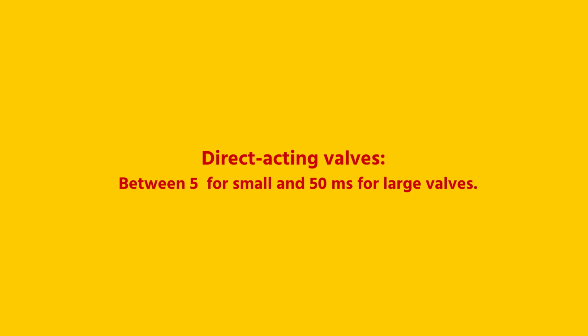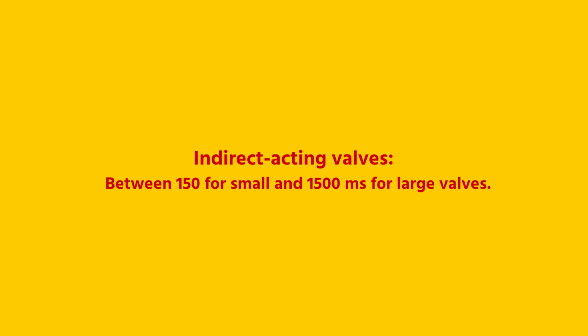Common response times for small direct acting valves is 5 milliseconds, and for larger ones roughly 50 milliseconds. For indirect acting valves, typically 150 milliseconds for smaller valves and 1500 milliseconds for larger ones. Keep in mind that a small response time can cause a water hammer, then opt for a valve with a longer response time.